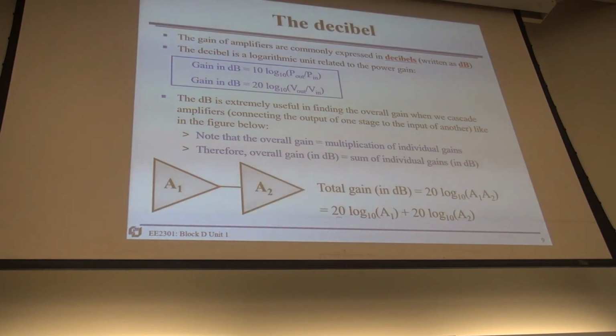So what's the end result of the amplification? A1 times A2. So you introduce the dB, it will convert multiplication to summation. You learn that. The reason to introduce log is to turn multiplication like this into the summation. So is this clear?